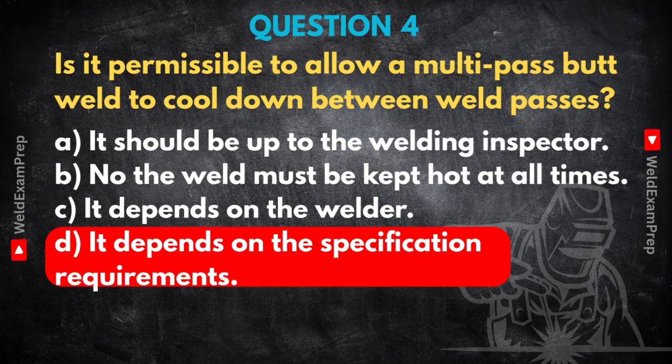It's carefully worked out based on the material, the thickness, the joint design, the intended use, everything. And it specifies temperatures. Yes. Critically, it specifies the interpass temperature range, a minimum and a maximum temperature the weld area must stay within before the next pass is added. Why is that range so important? It controls the cooling rate. Too cold, and you risk things like hardening or cracking, especially hydrogen cracking. Too hot, and you can get undesirable microstructures, like coarse grains, which reduces toughness. Sticking to the WPS ensures the final weld has the right properties, strength, toughness for the job.